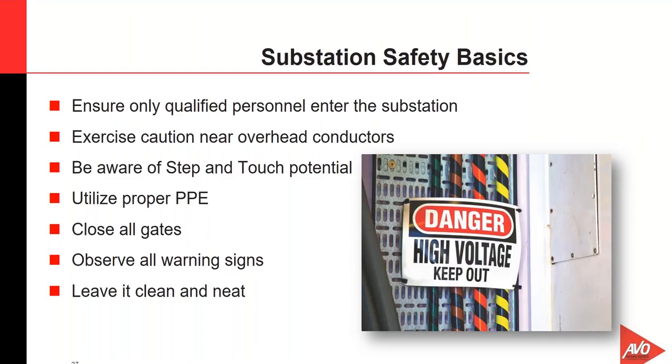As far as step and touch potential is concerned, I want to talk about making sure that we keep vegetation out of the substation. Okay, we don't want any vegetation. We want to make sure that we keep any type of rodents out of there. We want to make sure that the crushed rock inside of that substation is kept at a nice thick amount according to the IEEE standard, and so that we have no potential for flooding as well.